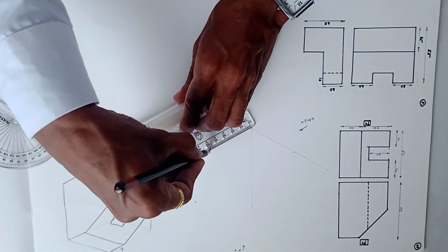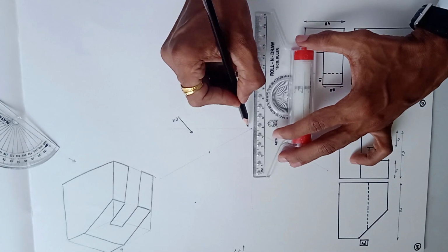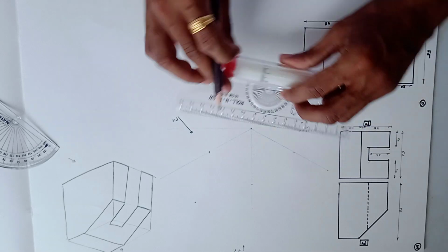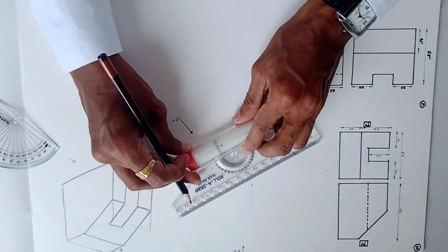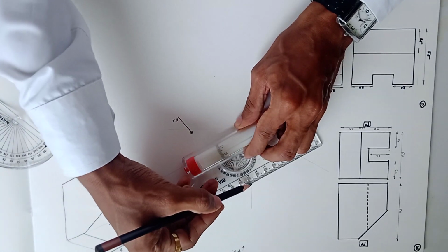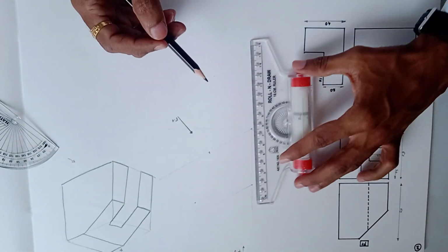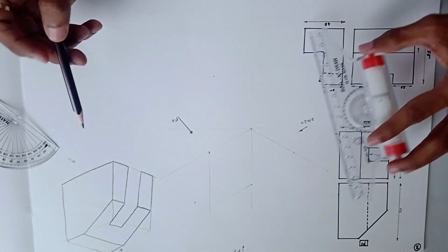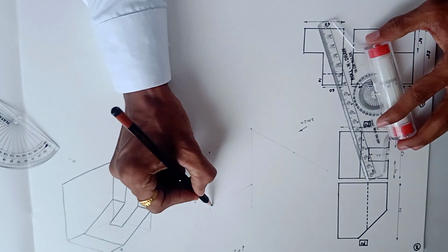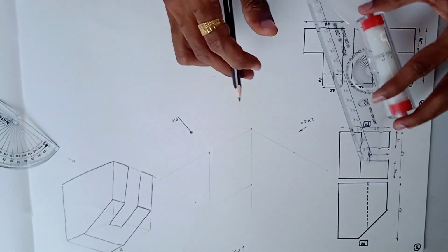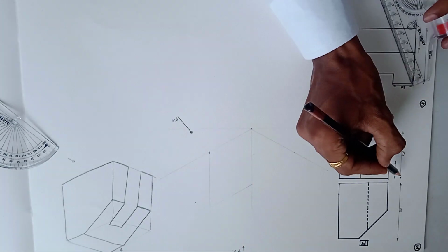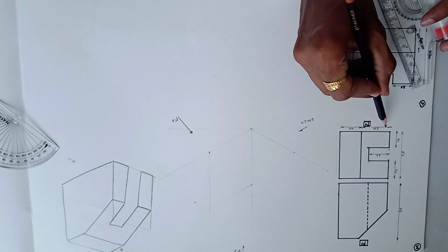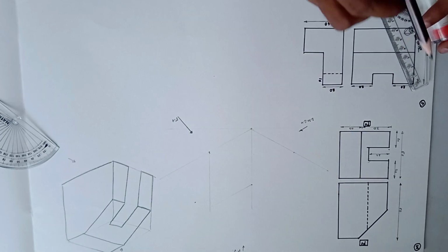So take this length 50 mm. From this corner take the height along y direction as 60 mm and complete the rectangle by thin line. Now if you observe in the top view, we will see this maximum dimension. Okay, so this is the width 60, length is same, it is 30 plus 20, that is 50.